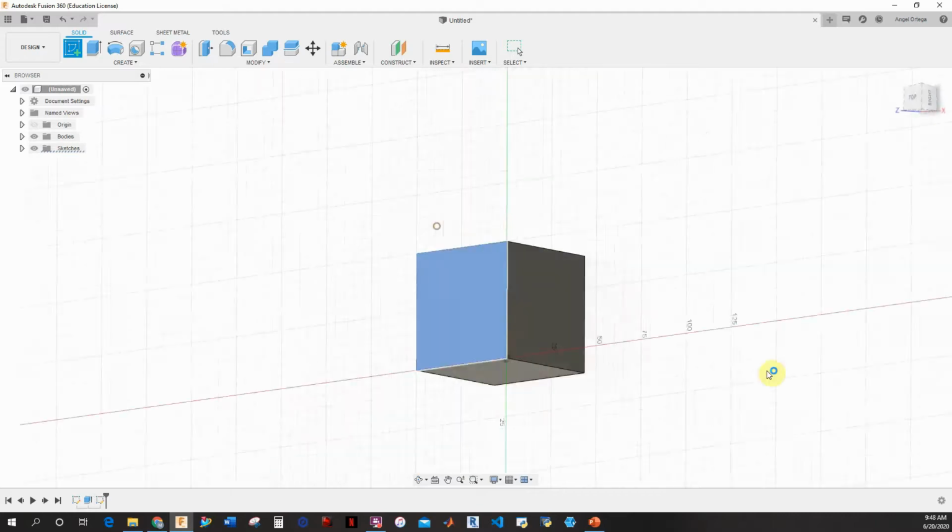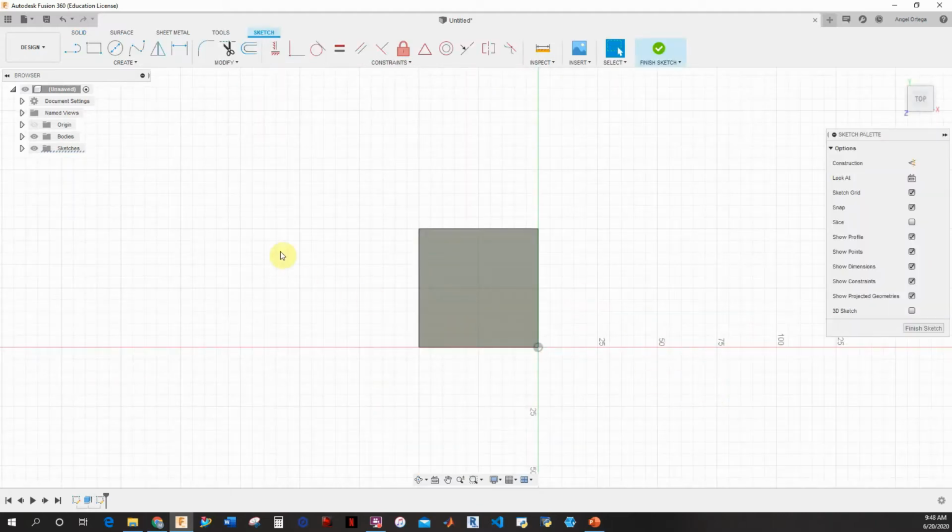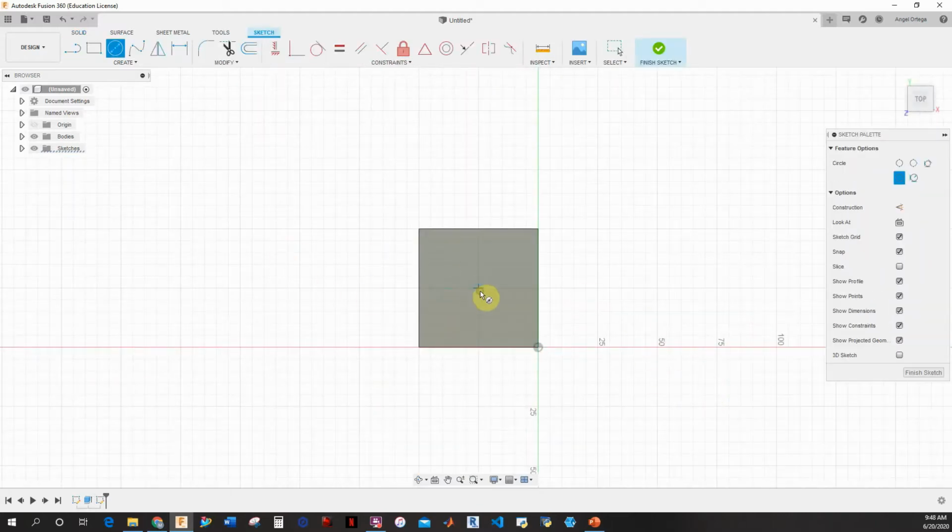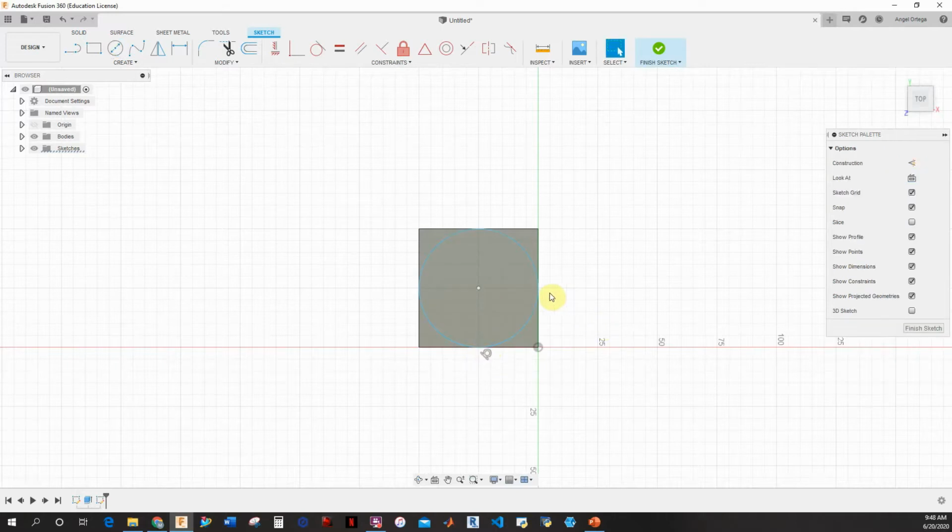So here I'm going to select that top face, and then I'm just going to create that circle like so. Now I can give it dimensions just like before, so 25 in my X, 25 in my Y, and of course it has to have a size, because there's a tangent constraint. It's taking this circle and making it tangent to this specific edge right here.